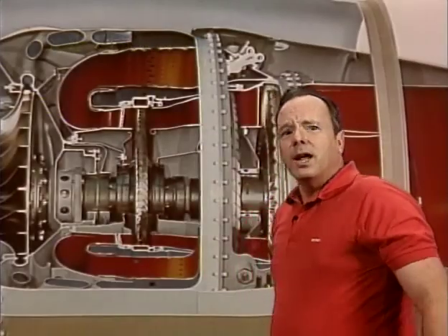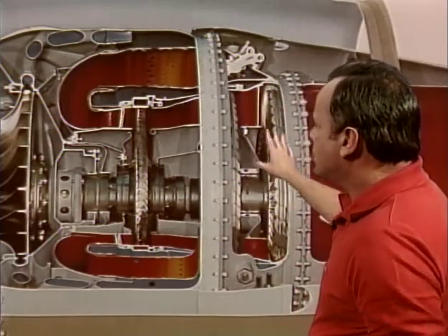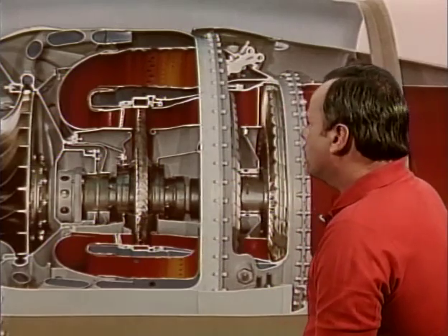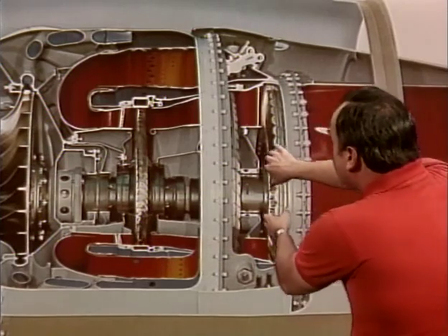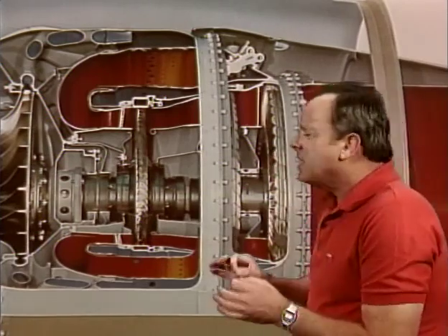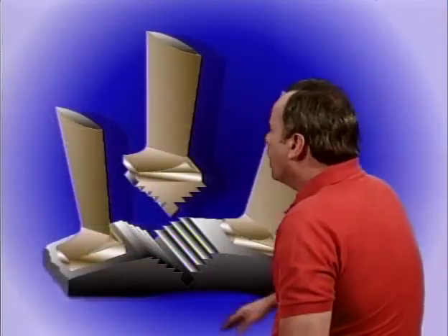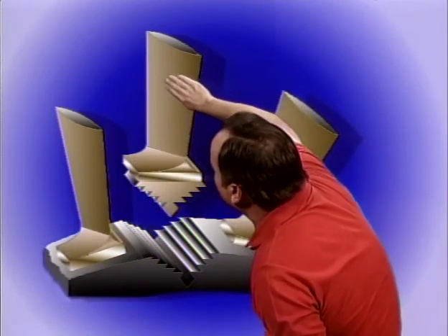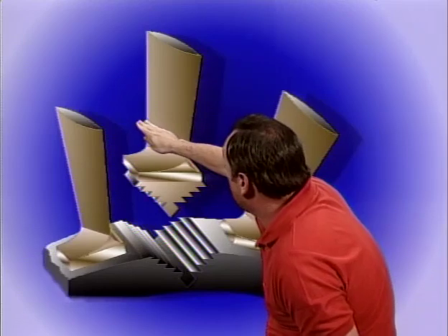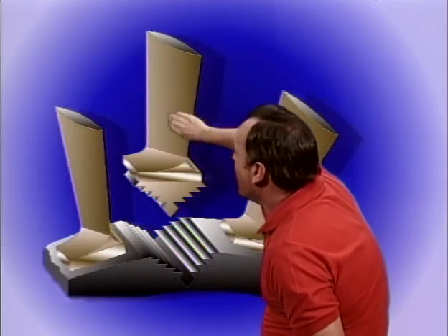Now, what would happen if you have over temperature conditions? What would it cause? Well, it would cause what they call stress rupture cracks in the leading edge of turbine blades and a possibility of turbine blade failure. So if you look at these turbine blades themselves, you might see a stress rupture crack, and that could cause turbine blade failure. Stress rupture cracks appear on turbine blades for turbojet engines across the leading edge to the trailing edge at a right angle to the blade length. So you'd expect to see stress rupture cracks go in this kind of direction, not that kind of direction.